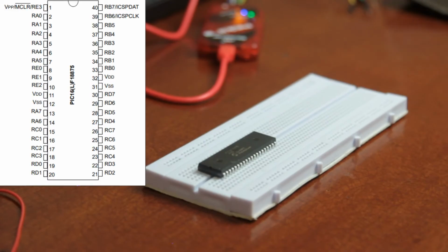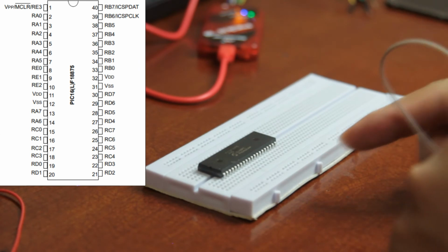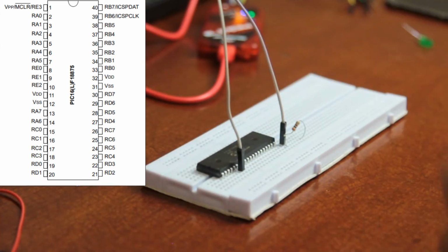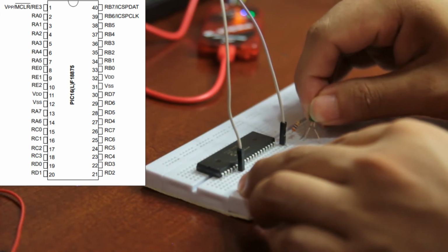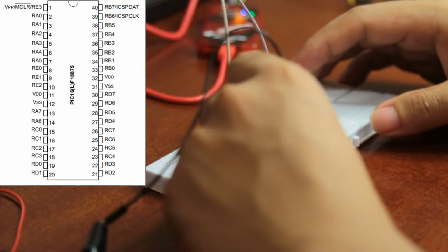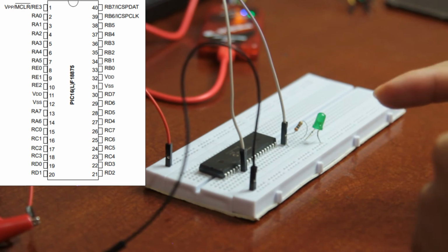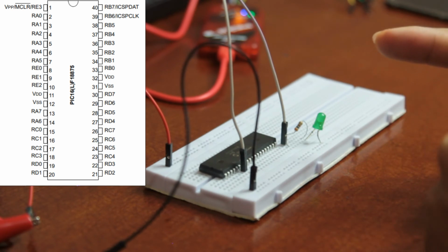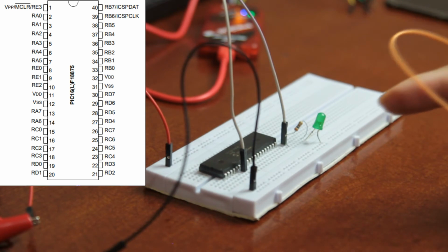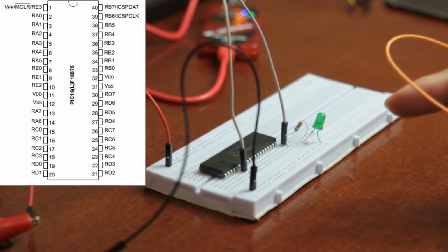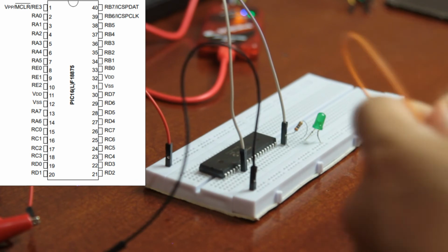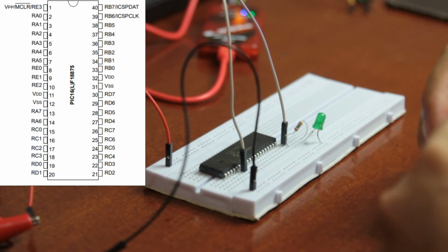For this experiment, we programmed the RA4 slot, which is the 6th slot of the microchip. We'll connect a connecting wire there. Then let's place a resistor. So let's connect the LED, then the negative to the ground and the positive terminal. For this microchip, all VDD and all VSS pins must be connected at the circuit board level. Allowing one or more VSS or VDD pins to float may result in degraded electrical performance or non-functionality. So we need to connect all VDD and VSS pins.